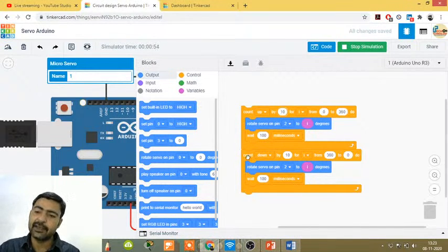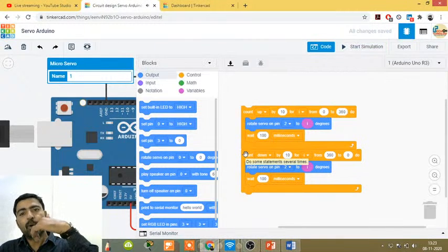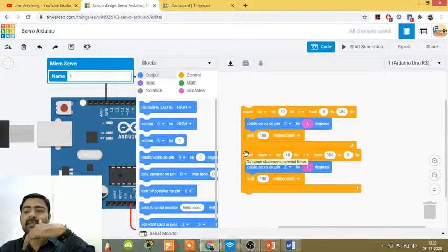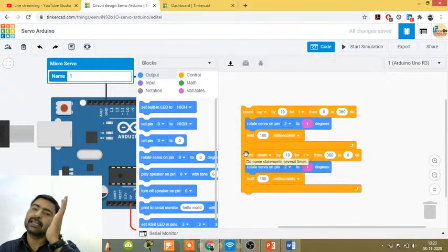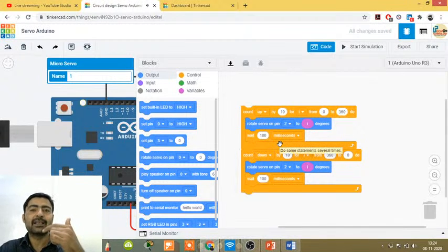Then in this second block, what is happening? That motor is running in the reverse direction, 360, 350, 340, 330, like this up to 0. So this count instruction is counting up, and this count instruction is counting down, and the count increment is not by 1.